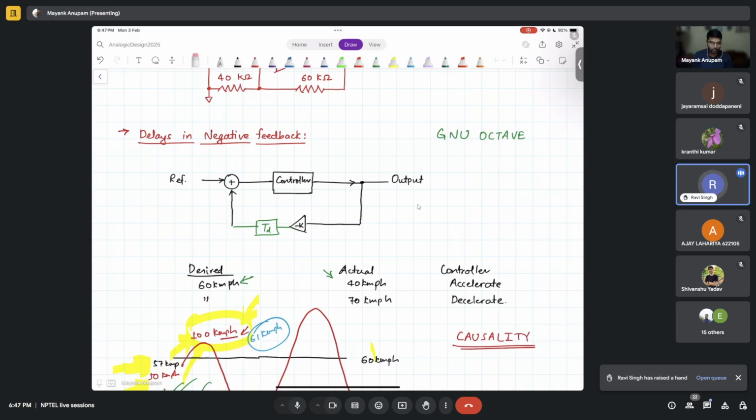And like you said, the unity gain frequency means we will have to compulsorily reduce the bandwidth of the system in order to make it stable, right? That will come later, but this is the intuitive understanding of that. If there is a delay in the system, you have to make sure that the loop actually doesn't work at very high frequencies. It is not able to process very high frequency signals. It actually has to slow down. If there is a delay in the system, the loop has to slow down further to respect that delay. Got it?